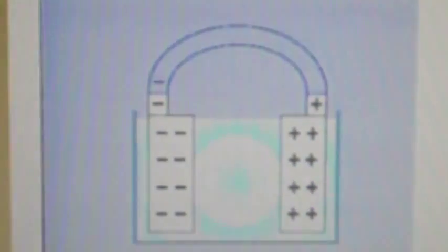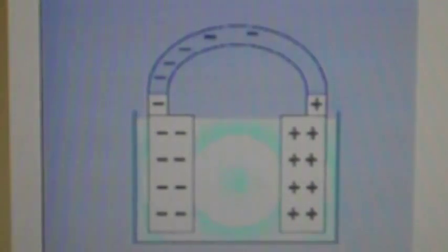This leads us to the 3rd condition needed for electricity to flow: a complete circuit. A complete circuit is simply a path through which free electrons can flow toward the positively charged atoms. If the negative and positive sides of the battery are connected with a good conductor, such as a copper wire, the potential difference or voltage will cause the electrons to flow from the negative side of the battery to the positive. This is current flow, or more correctly, electron flow.